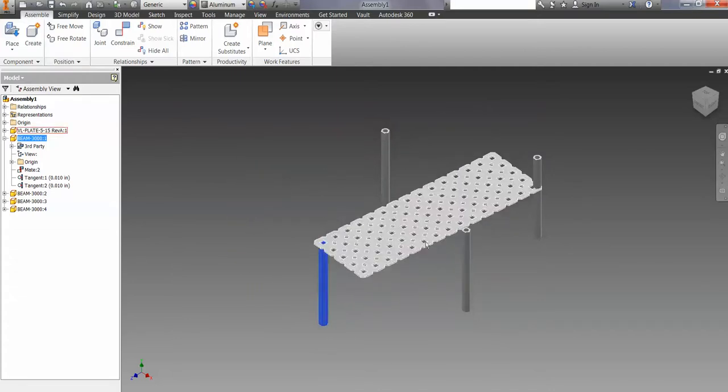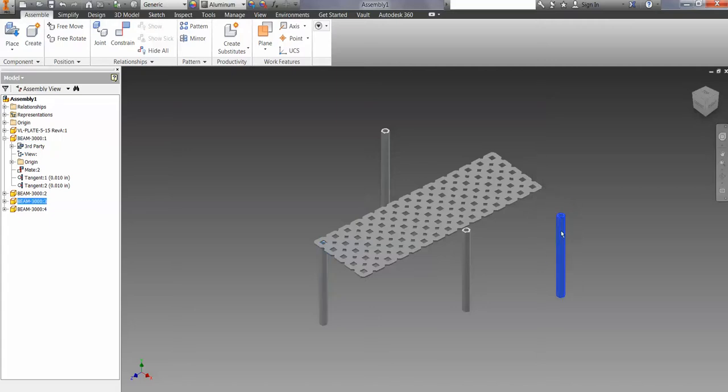So I can do the same thing with the other four at each corner, just like I did here. Do a mate on the surface and tangents for the inside to those squares. But also have other options of how I can put things on here that will help me line them up a little bit better.